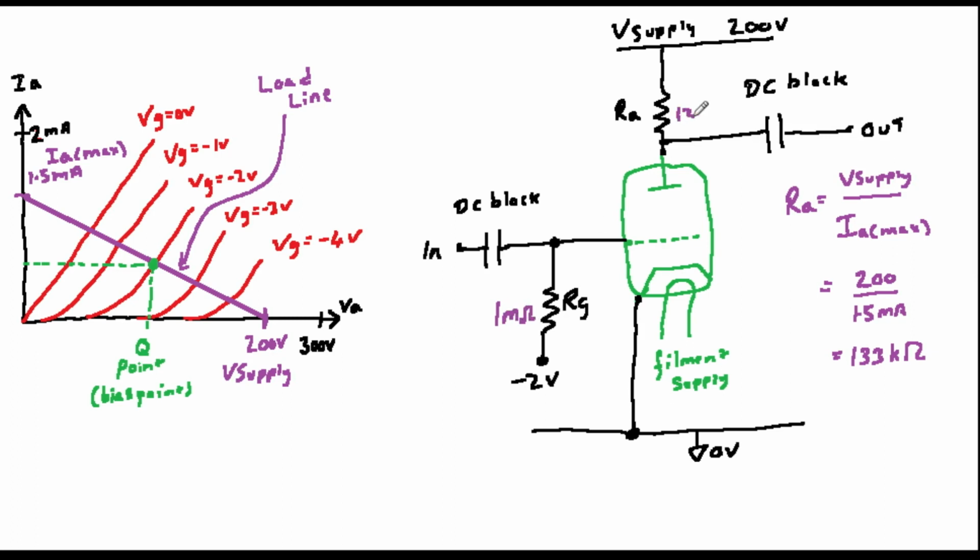As you can see, the amplifier works on more or less exactly the same principle as a constant gate bias FET amplifier. The DC blocking capacitors are chosen in the same way as in other amplifiers, in other words, to have a low reactance at the frequency of interest.